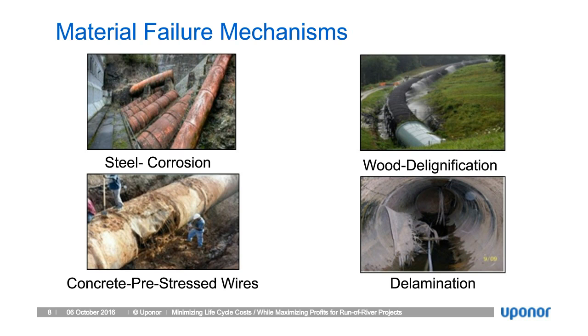Concrete with pre-stressed wires, which is the PCCP picture we saw previously. The concrete is a porous material, so once water gets access to the steel, it starts to corrode the wires, and when the stressed wires fail, you have a catastrophic failure within the pipe. It doesn't leak, it just bursts open. That's a real issue, particularly for above ground or buried applications, where when these pipes abruptly break, you could have extreme washout and a lot of damage in the local areas.